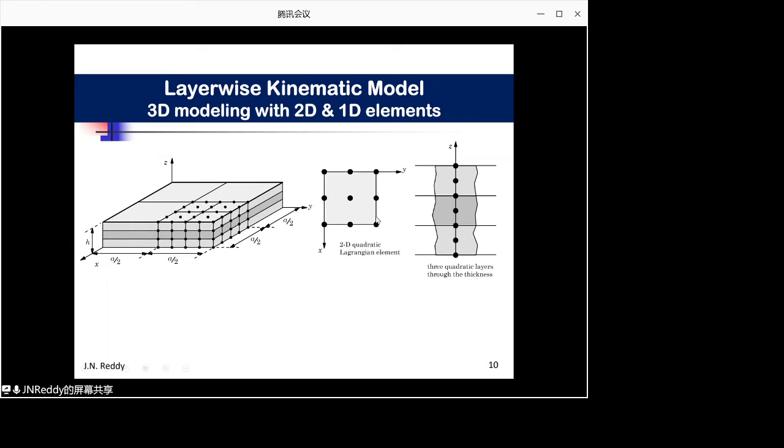That would have been the sigma ZZ and sigma XZ and YZ, which should be continuous. But the sigma XX is not continuous at the interfaces. Okay? So what I was commenting earlier is this jump is in the wrong direction compared to the elasticity solution. See, the jump is in this direction, whereas the 3D elasticity theory result is this solid line.